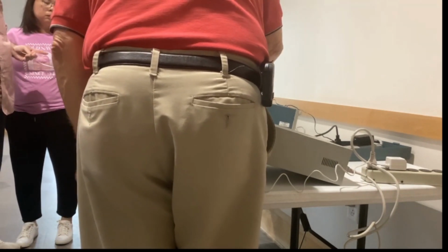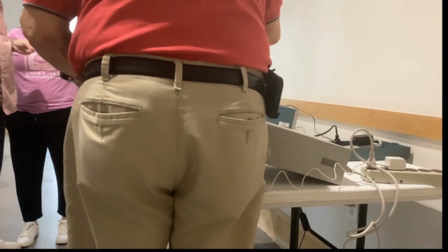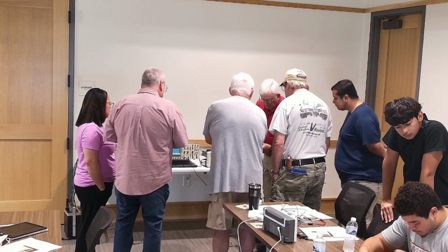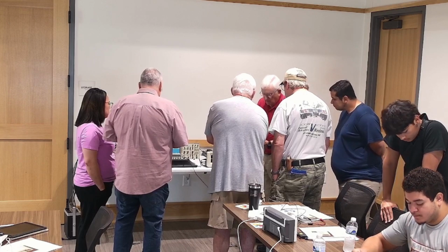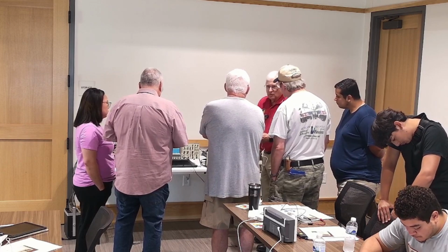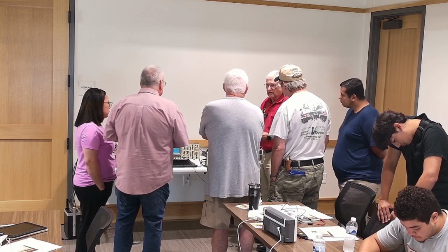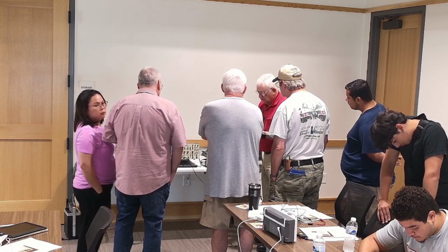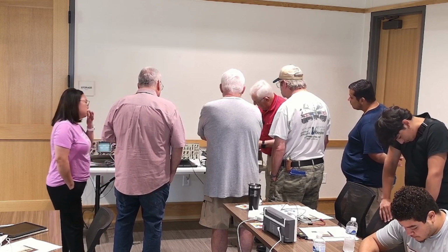By the way, one of the other little gotchas you have to watch out for on the probe. There's a setting times 1 or times 10. So if it's on times 1, 1 volt in gives 1 volt out. Times 10, 1 volt in gives 1/10 of a volt out. So you can use it like an attenuator. Okay, so let's see if I'm anywhere near right on that one.